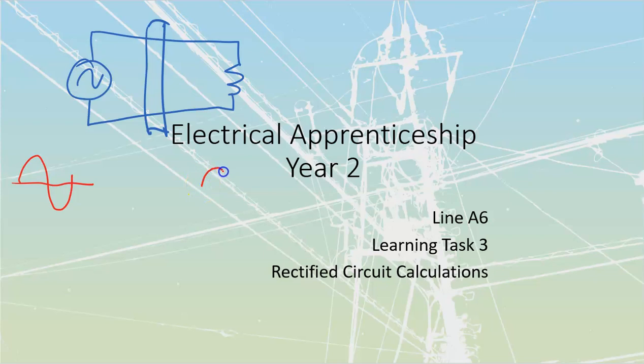But what it's going to do is take the same amount of voltage that we had on this side over here, if it's a full wave, and flip that over and drive it through here. Instead of current going whoosh through in this direction and whoosh through in that direction, we're now taking the current and driving it through whoosh in this direction, whoosh in this direction as well. Which means that in a full wave rectified circuit we are going to see the same amount of power put out. Just all of that power is going to be in one direction over here.